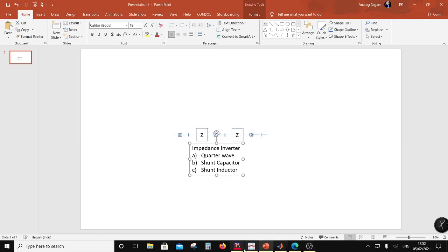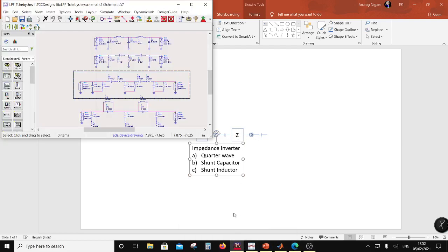So this bandpass filter, which looks like this, I can take the series elements, represent them as resonators, and the resonators can be just a lambda by 2 line, right? A lambda by 2 line can act as a resonator, right? And then you can have the impedance inverters in between, which can be some form of a discontinuity, which may be an edge coupling. For example,